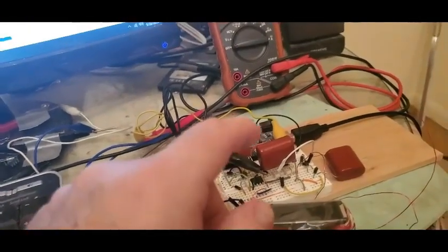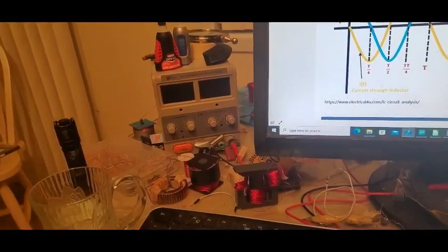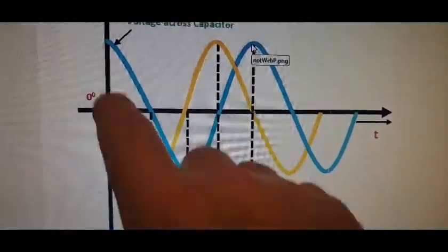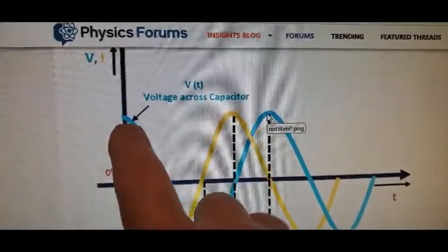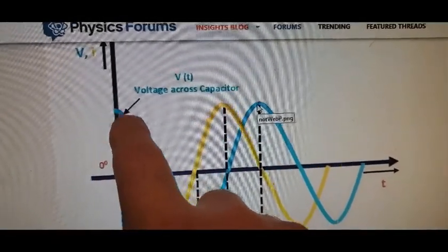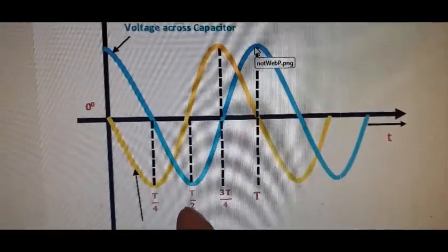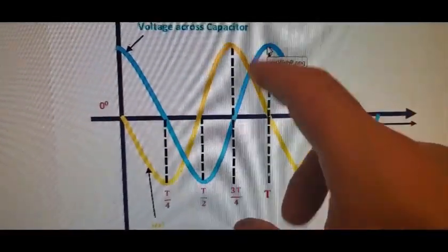At first thought you might say, well, if your power supply is at 10 volts, then the voltage is 10 volts going into the cap, simple. But recall, before we were showing the cap going down as far negative when I was doing the single pulses. So let's say you have a 10 UF cap here, and then it goes to 0, and you interrupt it there. Now you're at negative 10, and to get back to 10, you need 20 volts.